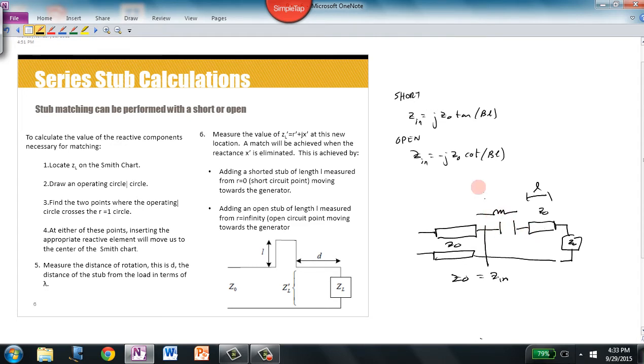The problem with this is parasitics of these devices. Inductors and capacitors at high frequencies are relatively poorly behaved devices that don't exhibit the properties that we would expect. This is for a variety of reasons. In this class, all you need to know is that's the case. Inductors and capacitors don't behave well at high frequency. Fortunately, when designing matching networks, we have an alternative.